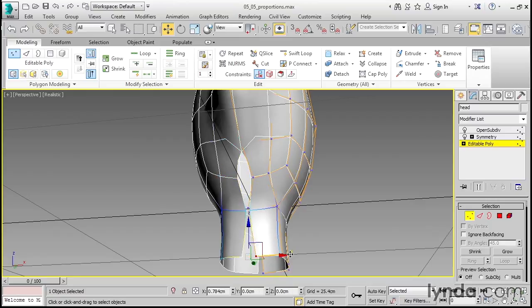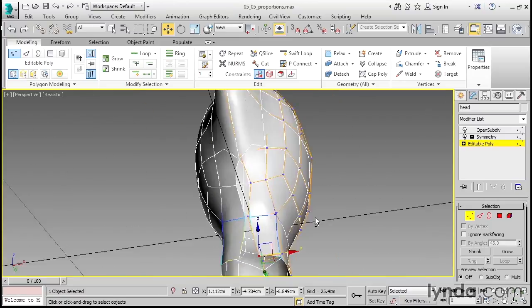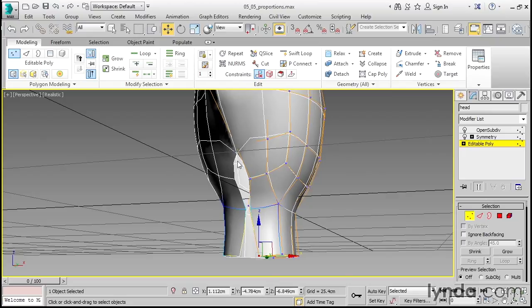As you work and do various commands, some of those points are going to get moved around, and you want to place them all back at an X value of 0. But you can't really do that on multiple selected vertices by using the Move tool. They will move if you type in a 0, but they'll all keep their relationship to one another, and they won't flatten out as you need them to.